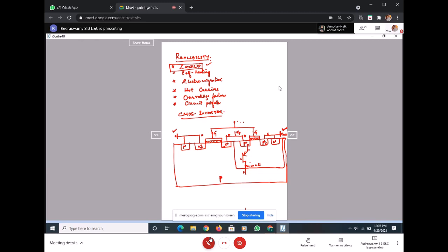So this is N, this is P, and this is N. Is this clear? And this P and this P are the same, so they are shorted. All of you are okay till this point? Okay. So we have two BJTs existing within this particular CMOS inverter.